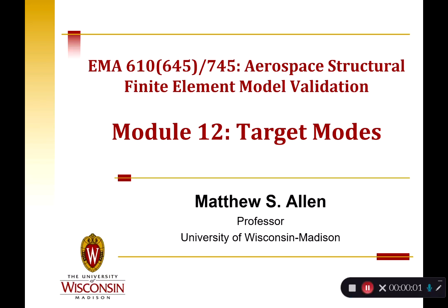Today we're going to talk about how to determine target modes for a finite element model verification or validation or model updating study. Any real structure has an infinite number of modes to choose from, and even a finite element model might have hundreds of thousands or millions of modes that we could choose from. So we need some strategy to determine which modes we care about.